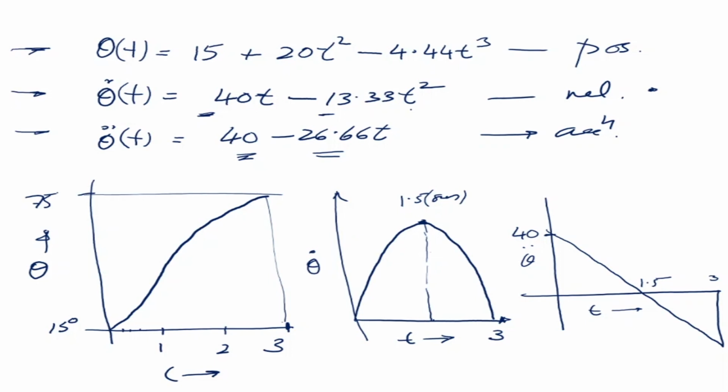Now the question that is important and interesting here is: is this possible? This is a real robot, a real single link which is rotating, and we are fitting a cubic polynomial and want to move it from rest to rest in some time tf. If we do that, then when we plot the position, velocity, and acceleration, it comes out like this. This is the variation of position, the one on the extreme left. This is velocity, and that's acceleration.